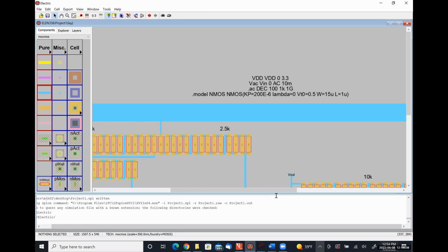One of the things that I dislike the most about LTSpice is that there's not a way to do this for BJTs. There's a way to approximate it so you can set your beta values, by saying, treat all my BJTs as a particular type of BJT and then change the beta value to this. But you can't, or at least I haven't figured out how to change the saturation current parameter, IS, for the built-in models. So that's why it's annoying to me, because otherwise we could simulate all of our circuits in this class, and I'm sure you guys would want to beat me to death in the street.